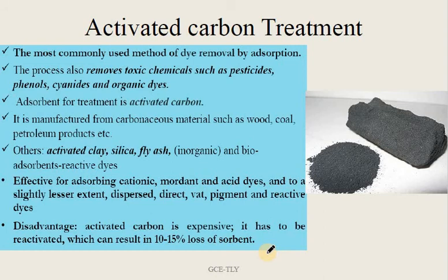The disadvantage is that the activated carbon method is effective but it has to be reactivated. This can result in about 10 to 15% loss of the sorbent. So that is a disadvantage. Other than that, it is a beautiful technique to remove color from wastewater. The only thing is that it is somewhat expensive and it needs regeneration.